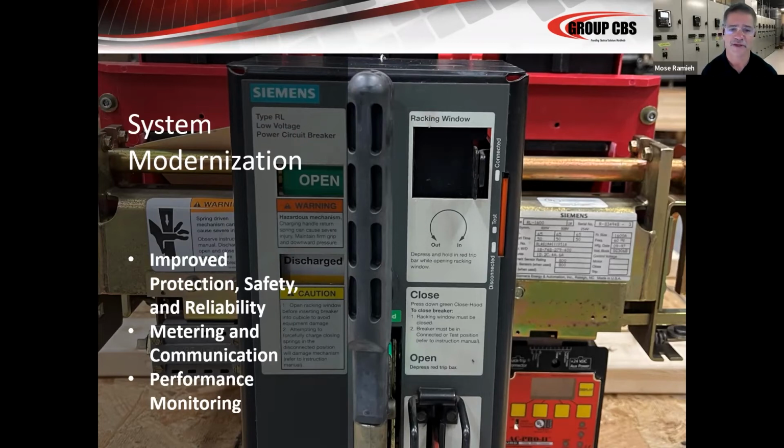And then what we might find is that the breaker needs some additional maintenance, right? Because once again, our coordination study and our arc flash studies are based on these breakers operating by design, right? If all of a sudden we have a breaker that's operating just a little slower, that's going to make our arc flash hazard just a little higher, right? Just a little higher. So once again, the sluggish breaker feature that is now in some of these trip units is spectacular for knowing, without even doing maintenance, hey, is this breaker operating properly?